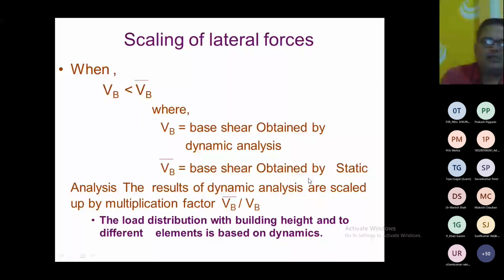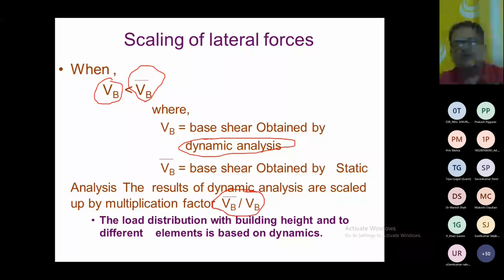But here the important thing is this: the base shear we are taking from the dynamic analysis. If the base shear obtained from the dynamic analysis is less than the base shear obtained from the static analysis, then we have to apply this multiplication factor to the results we are getting for the dynamic analysis, right? So that is very important.